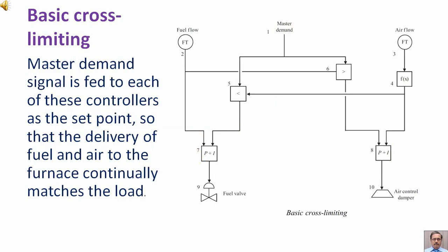Master demand signal is fed to each of these controllers as the set point so that the delivery of fuel and air to the furnace continually matches the load.